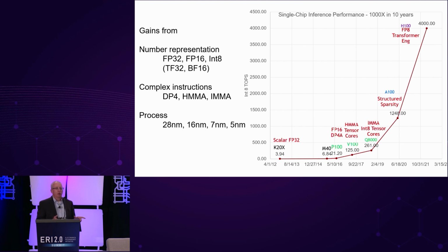That is 4 times the size of the FP8 that we really needed. And because multiply is the thing that dominates the energy, it was 16 times the energy. So 16x was just going from FP32 down to FP8. And along the way, we went to FP16. We found that we could train most networks in FP16 if we scaled them well. I'll talk more about scaling later. For inference, we moved to INT8 in the Turing generation. And in the Ampere generation, we introduced structured sparsity. I'll talk some about that.